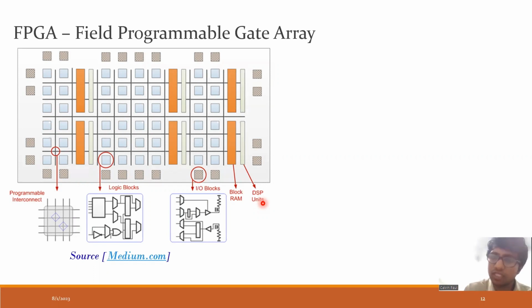In practical real life we will not be just implementing an AND gate or an OR gate. It is a complex function made of multiple AND gates, multiple OR gates connected in various fashions. So we cannot go into designing that in specific detail. Hence, we use the FPGA to translate our logic into a certain hardware setup which can implement our logic. That way we can change the logic using the same hardware. We don't need to change the hardware, or bring a new set of transistors and design it all over again.